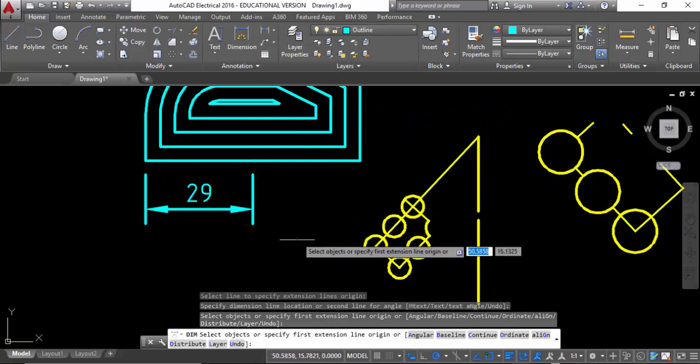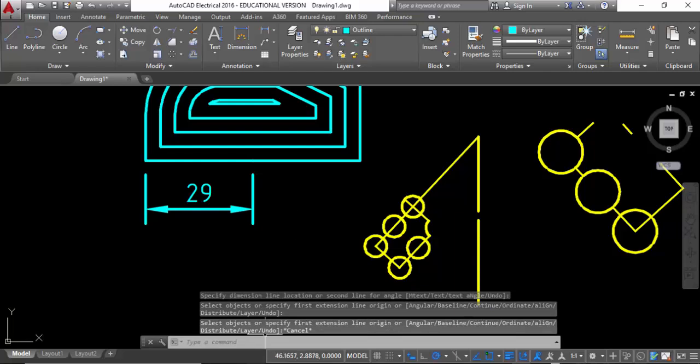So we generally will have another layer for our dimensions, and we make sure that that layer is going to reflect everything as far as our standards are concerned. So whether the line is thin or whether it's thick, or whether our text height is, it must reflect what the text layer thickness must be, and the dimension line itself also must reflect what the line weight must be, what the thickness of the line must be. Okay, I'm going to press escape.